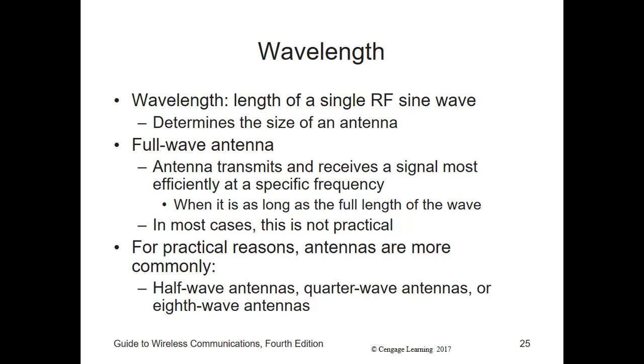Now, when antennas have a higher gain, with a higher gain required, you can increase the size of the antenna to the next bigger fraction. A larger antenna would exhibit a higher gain than a shorter antenna. Almost any metallic object, or any object that conducts electricity, can act as an antenna. But if you use an antenna that is much shorter than the wavelength of a particular frequency, it will not radiate any significant amount of radio frequency.